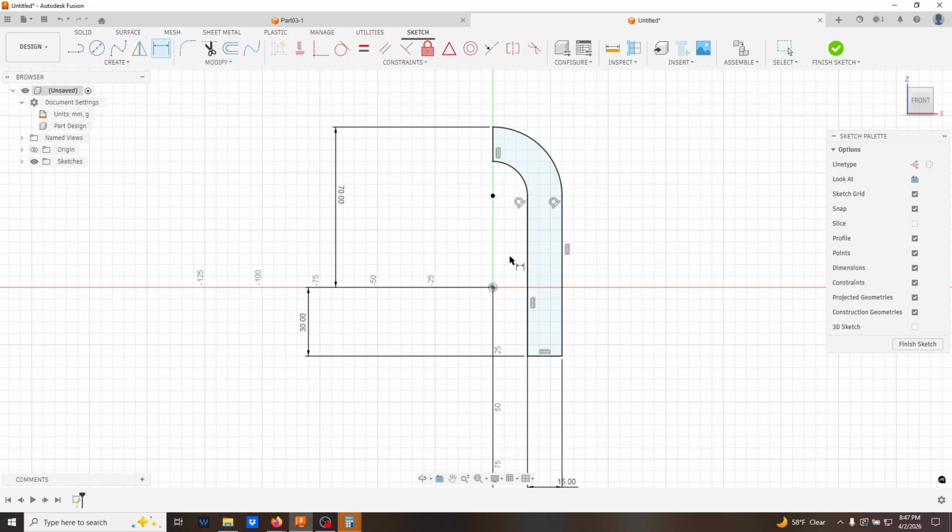So how it can change can be different, specifically with the actual location of this hole that we're going to put here. We talk about manufacturing tolerances of plus or minus 5 thousandths of an inch, but since we're doing metric, let's just say plus or minus a millimeter, to make the math easier. So this dimension up here can be as big as 71 or 69, and this one here can be 29 or 31. And just because I'm rambling now, if you read this in the comments, let me know if this explanation makes sense, because sometimes I get crazy when I say this stuff. I really just want to find better ways, because I think this stuff can be understood. Just sometimes people explain it in weird ways.